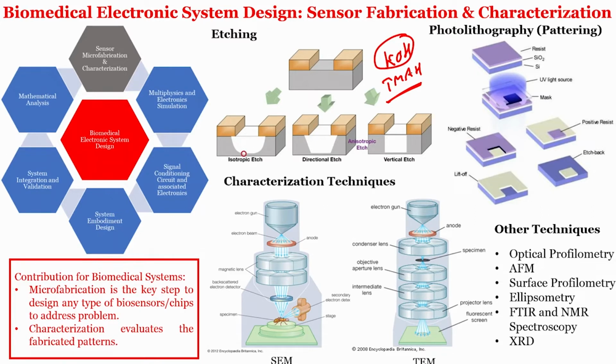In KOH the walls that you see are rough. In TMAH the wall, this wall, right, is smoother. TMAH is neurotoxic, KOH is not. But everything should be used under the wet bench environment with a proper exhaust. So, again, why are we learning lithography? Because we want to understand how the patterns are formed. Why are we learning etching? Because finally the sensor is fabricated, right.